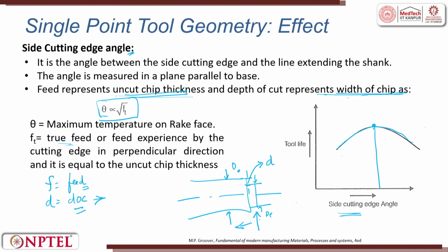So, this is the tool, right. I will make a tool here. Assuming that this is a tool, the tool which moves along the axis is called the feed rate. This is called a feed. The feed will always be defined as a feed rate. So, feed rate will be defined as mm per revolution or mm per minute.